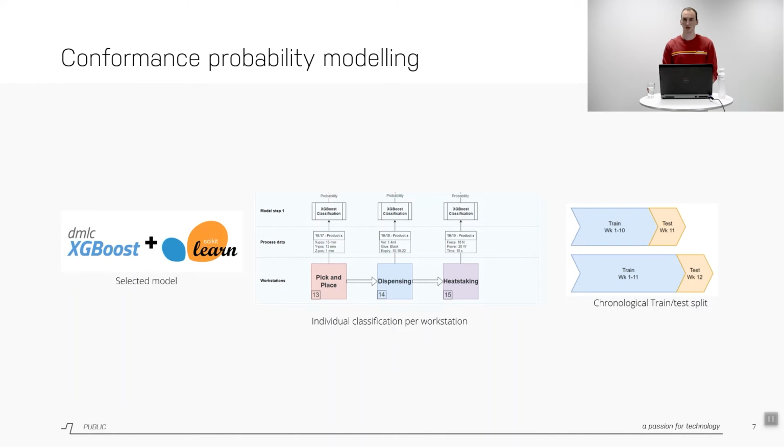We use the chronological train test split because we have seen that in the beginning of the data set there were quite some process changes. Therefore, if we shuffle data around, for instance for cross-validation, you're going to train your model with future known data when changes have occurred, and then your performance is actually better than it would be in real life. So we decided to keep the data in the correct order and made a prediction at each week of the production process.